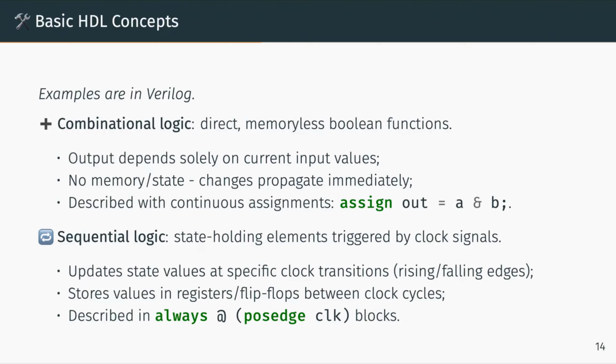Oh, yeah, that's a good question. We're using a hardware description language here, writing Verilog code, so we're inclined to deal with the very details of the clocks. We want it to be very precise in timing. If we want the design to be done in 100 clocks, we do not want it to be done in 101 clocks. There are use cases like high-speed interfaces where we have to have very precise control of this kind of logic. At that time, we certainly need to write HDL code, so it is useful for interfaces.